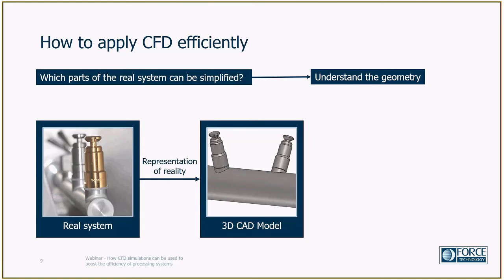However, when we are building our CFD model, we need to think about whether we really need to include all these details, whether they are going to have any effect on the final solution, or whether we can just make a simplified version of these nozzles, for instance. The key aspect here is to think about whether we can simplify the geometry without paying a big cost in accuracy of the results.